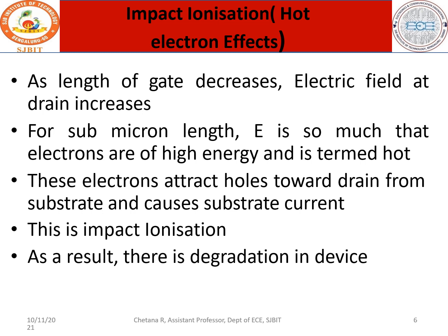This is called impact ionization, and therefore the device is degraded. So this is another non-ideal effect, something which is not desirable. So try to avoid the leakage current flowing, because you already know about hot electron effects.